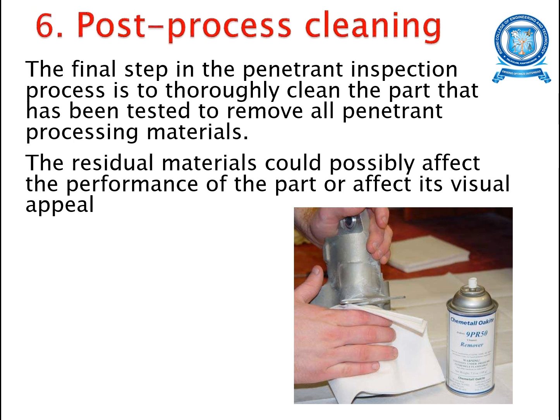And the last step is the post-process cleaning. This is the final step in the penetrant inspection process, in which the part is cleaned properly after testing to remove all the penetrant processing material, because the residual materials could possibly affect the performance of the part or affect its visual appeal.